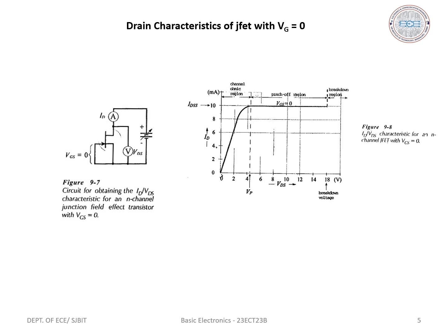So from region VDS equals 0 to VDS equals VP in the graph, the channel acts as a resistance, and this part is called the channel ohmic region. If VDS is increased, a voltage is reached at which gate channel junction breakdown occurs, ID increases, and the device may be destroyed. So the pinch off region is the normal operating region for the JFET.